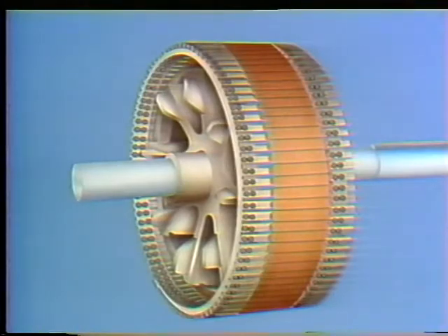Don't bother looking for shorts in a squirrel-cage rotor. The rotor bars are already shorted together intentionally by end rings. The squirrel-cage conducting bars aren't insulated from the rotor either, so grounds aren't a problem in a squirrel-cage rotor. But opens can occur. When a rotor bar separates from its end ring, an open occurs in the current path. A visual inspection of the rotor bars and its end rings is all that is needed to verify an open in a squirrel cage motor.